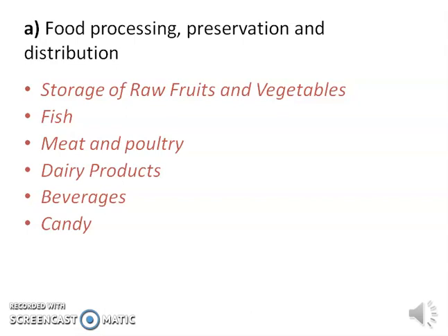Ice cream manufacture requires pasteurization through mixing, emulsification and stabilization, and subsequently cooling to 4 to 5 degrees centigrade. This is to be cooled to the temperature of minus 5 degrees centigrade in a freezer where it stiffens, but still it remains in liquid state.